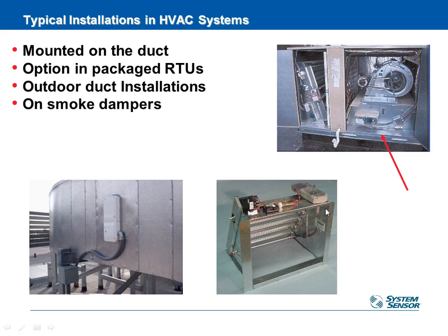And then the last place you might see mounted is at smoke dampers. We don't do a lot of smoke damper work at our office, but other folks do, and these same detectors can be used in those applications, obviously with a much shorter sampling tube in most cases.